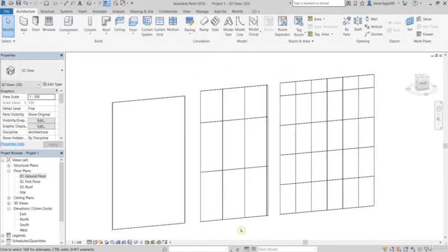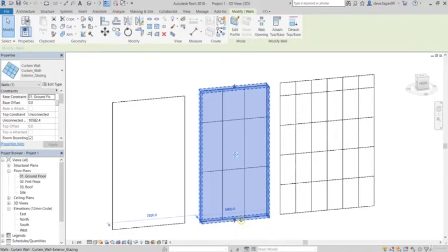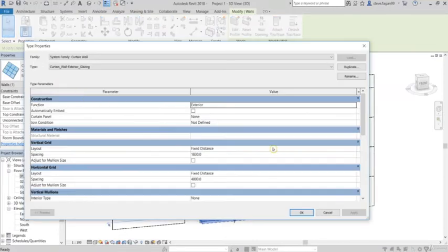So to go into the exterior glazing, if I select the curtain wall itself, again, selecting the actual curtain wall, I'll get this representation around it. So I get that dashed blue line around it. Select it, come into my properties section here. If I scroll down, I'm able to change the vertical grid in itself. So its justification, its angle, and its offset, as well as a horizontal grid. If I further go into the edit type, in here there's again more parameters for me to change.